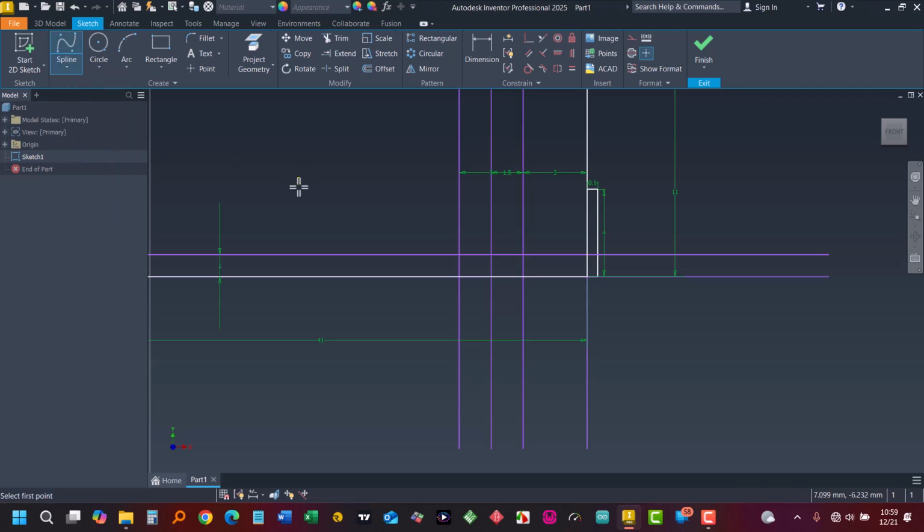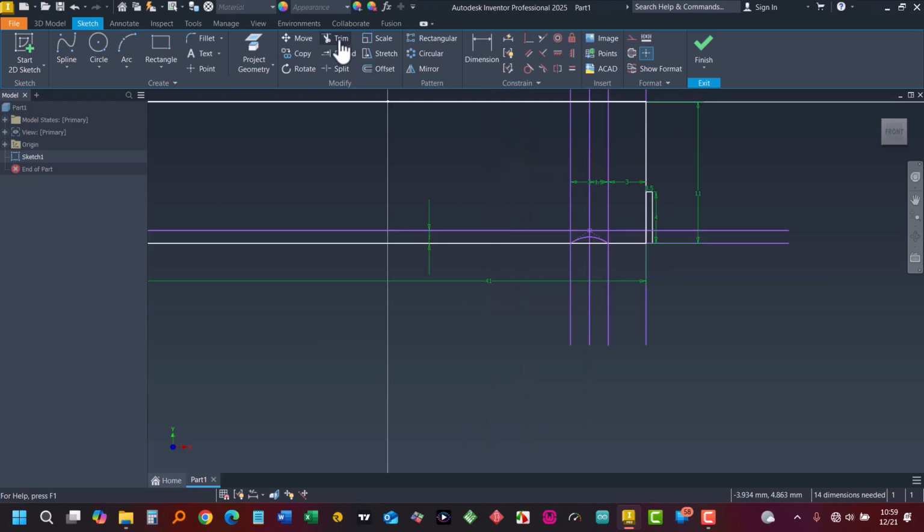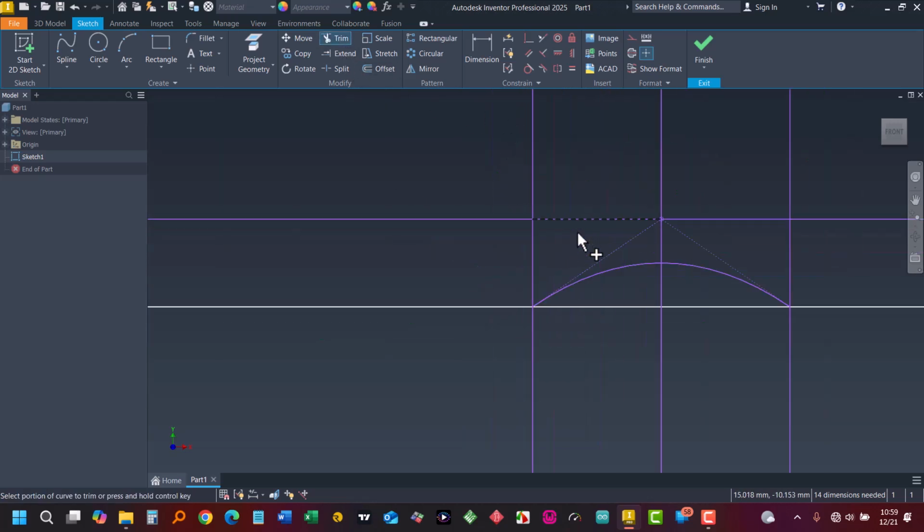Click the Line tool on the menu and select the spline icon. Draw an arc with 3 points using the 3 vertical lines. Click the right symbol to accept the arc. Pick the Trim tool and cut out unnecessary lines of the object.